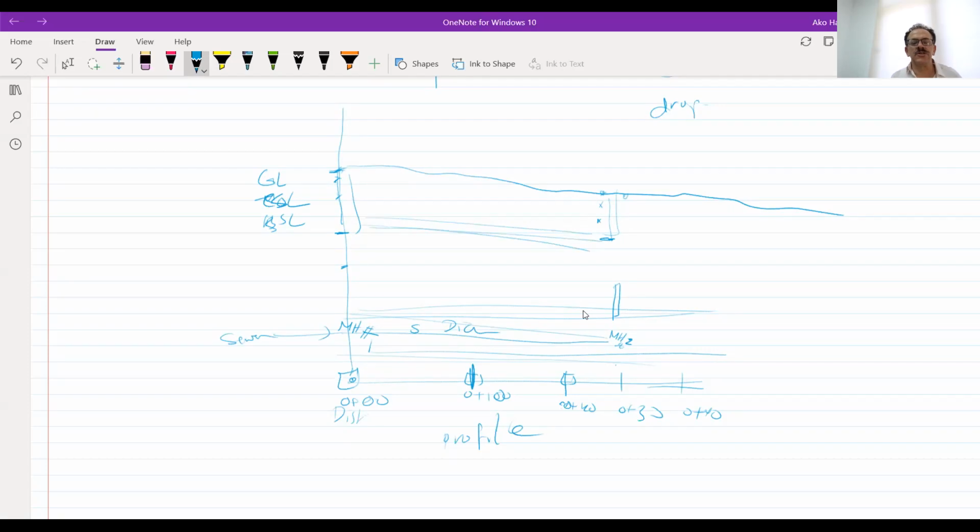Usually the engineers and the people working on the site need this profile. They are working from this profile. And usually for each profile, my advice to you is not to include more than 5 manholes in one chart, because the chart will become like 2 A4s.